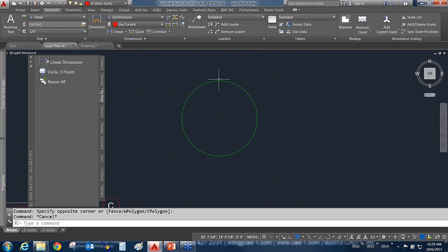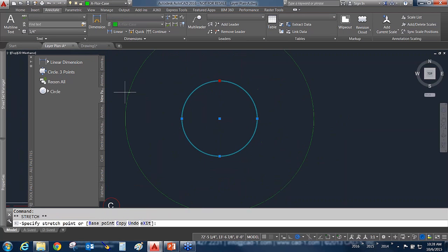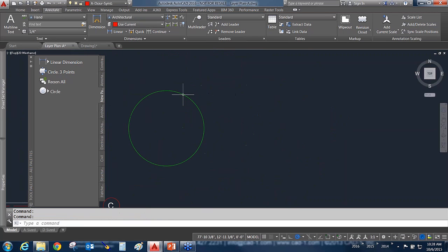This keeps everything organized, and it's very easy for anybody to work with this. It maintains all of the styles, settings, layer settings, all of the properties basically involved in this. Now there's something else that it does. When I drag and drop this, you'll notice that as I'm dragging and dropping, I'm not grabbing the grip. Don't grab the grip. That won't do any good. You drag and drop it from some other place on there.